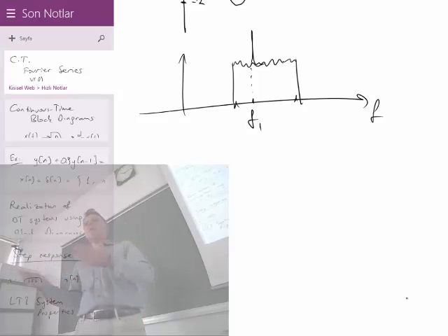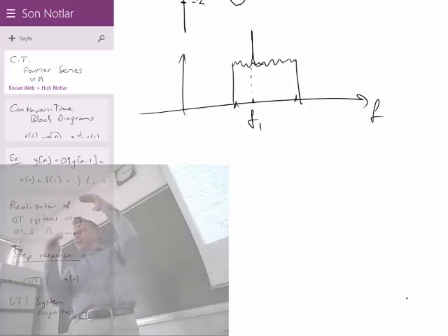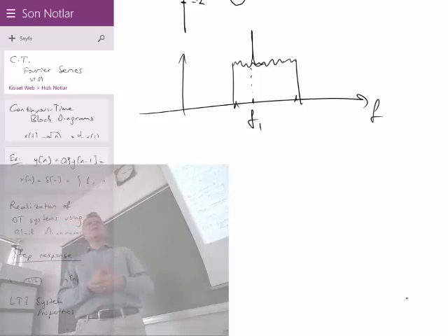For those of you who could think of audio compression as a project, here's the deal. An MP3 standard is like this. You have to quantize, level the information to reduce the number of bits. Normally it was like 16 bits for every sample. But if you use 8 bits for every sample, then it will be a worse music because the quantization levels would be more coarse. But it will be smaller.